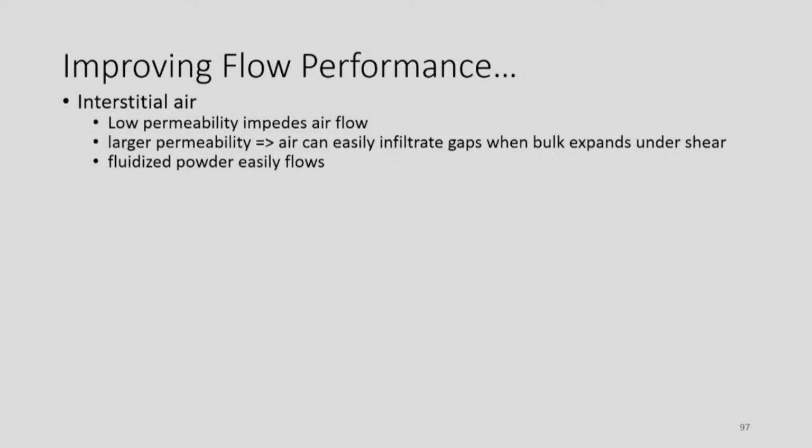Wheat flour unloading: in industry you always see additional pipes of air flowing through the trucks and containers so that the material will flow, because of low permeability. Larger permeability or larger white space will be better for flow. So if you can make the size distribution more uniform, a tighter distribution, then the flow will be easier.